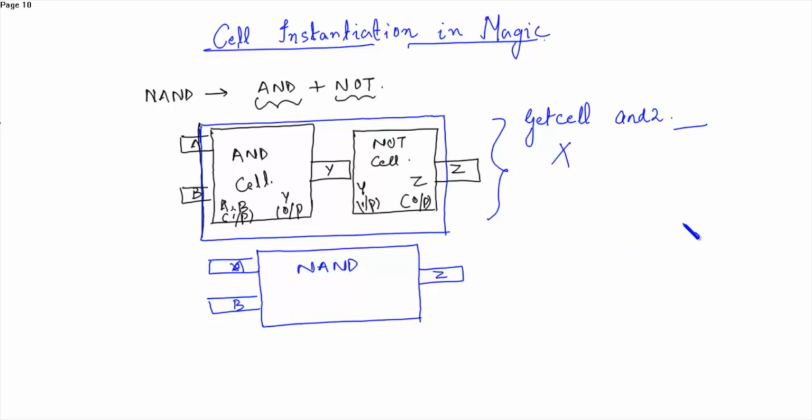So this is the third way followed in order to draw the layout of a NAND gate. In this schematic also we had A dot B. Actually we designed the A dot B, which in complementary form we obtain as A dot B bar as the output. So this is all about the schematic and layout. And AND plus NOT is NAND.